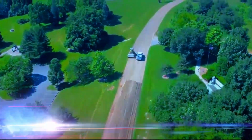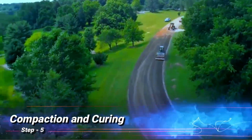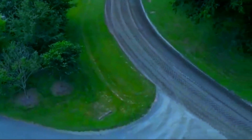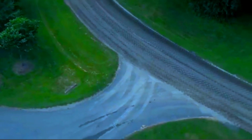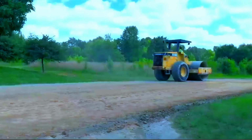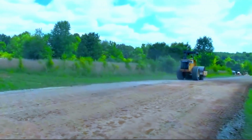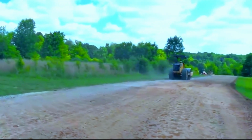Step 5. Compaction and curing. Next, vibratory rollers compact the material to achieve maximum density and strength. If a chemical stabilizer like cement is used, the material may require a curing period of 3 to 7 days before the final surface layer is applied.